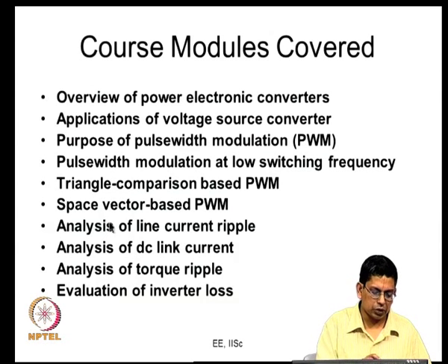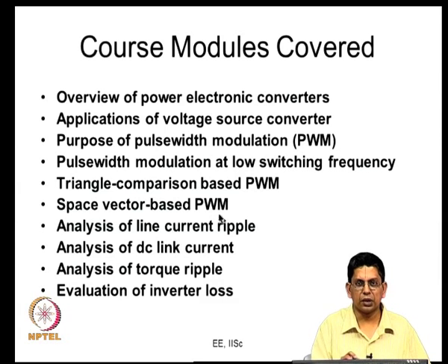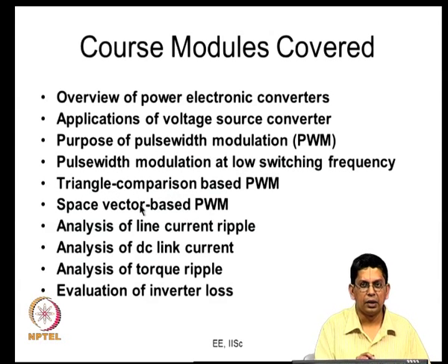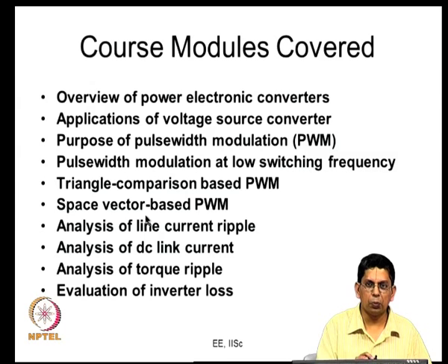Historically this was seen as something and that was seen as something else, and later on they realized that there are lots of similarities between the two, and at some point of time it was felt that they are entirely the same, meaning it is just an approach to how you implement whatever PWM waveform you can generate by comparing some set of 3-phase modulating signals against a triangular carrier. You can do the same thing using space vector based PWM, and whatever you can generate using space vector based PWM could be generated by comparing appropriate modulating signals against a triangular carrier, was the generally held belief.